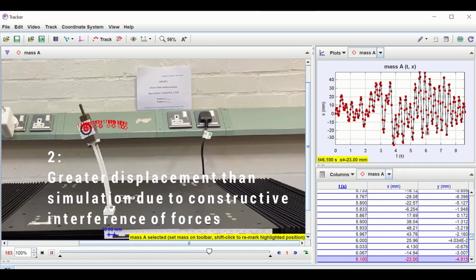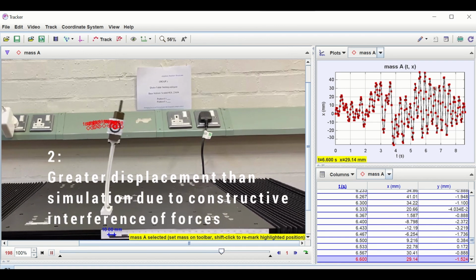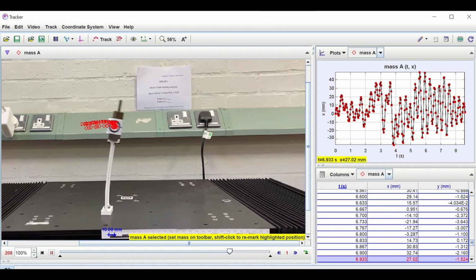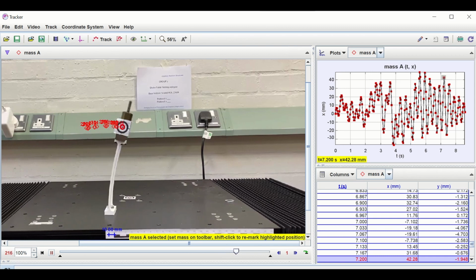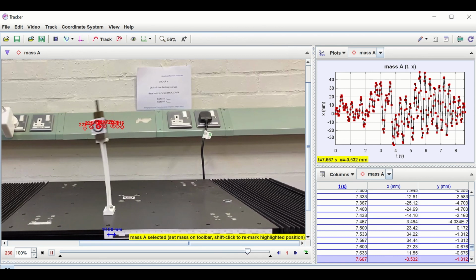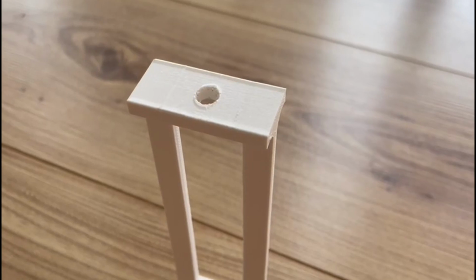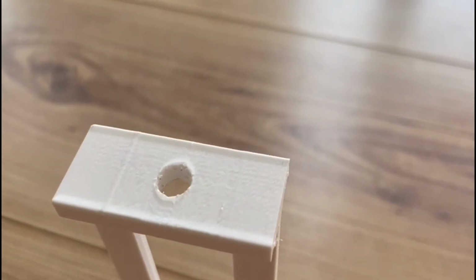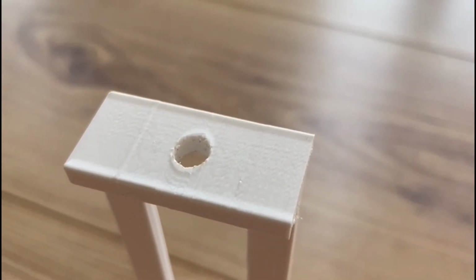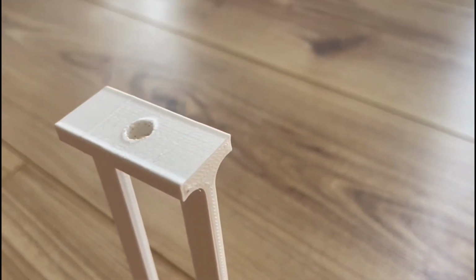Secondly, it can also be observed that the real displacement oscillates far more than in the simulated response. Therefore, the period at which the maximum displacement occurs is also largely different to the simulated waveform. Considering that the results of the most significant displacement are not the largest acceleration nor velocity peaks present in the earthquake spectra, this is rather peculiar.